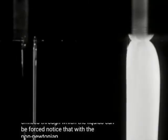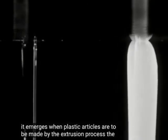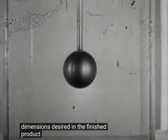Notice that with the non-Newtonian fluid, there is a considerable expansion of the stream as it emerges. When plastic articles are to be made by the extrusion process, the die must often be designed smaller than the dimensions desired in the finished product.